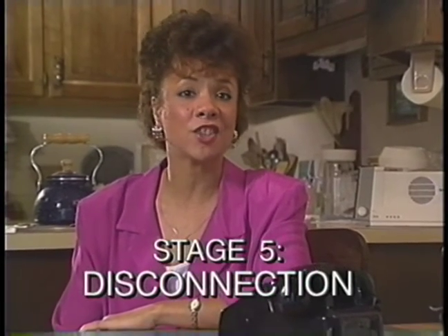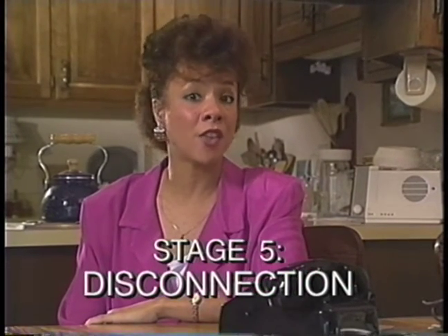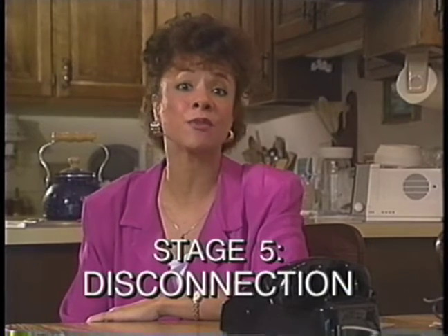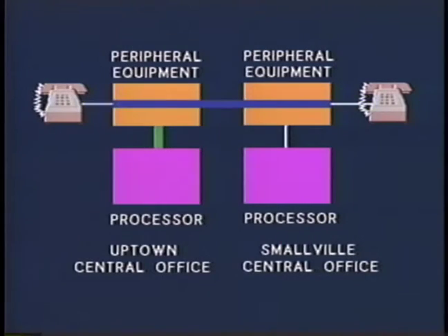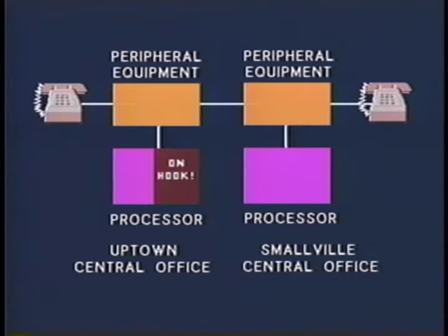When we shared our weekly news, I say goodbye, hang up the phone, and the final stage of call processing begins, disconnection, which may be performed by either office, depending on which line hangs up first. When the switching system detects that the state of my line has changed to on hook, it waits for a short period and releases the voice path between Zelda's telephone and mine. The billing register, if necessary, records the time of disconnection.